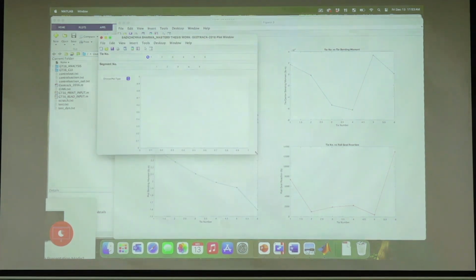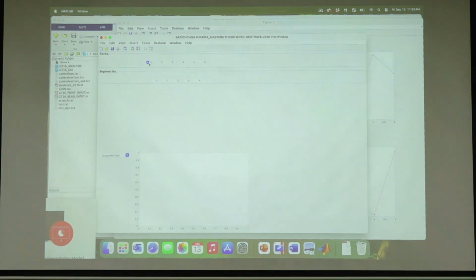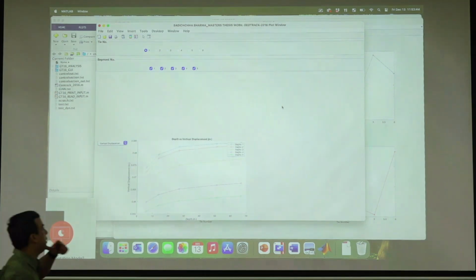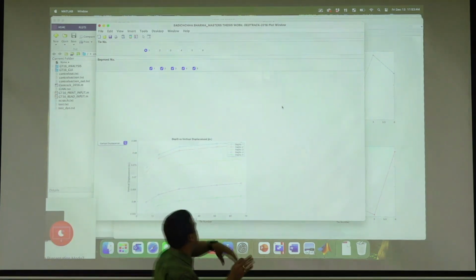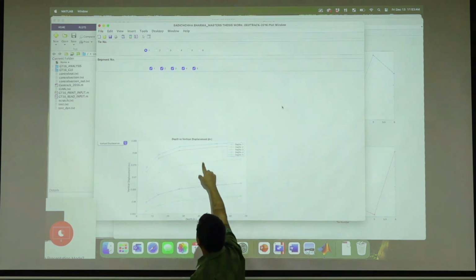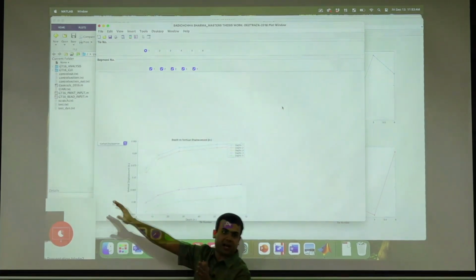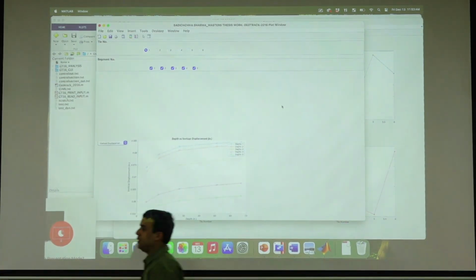But not only that, we developed this open-ended plotting window, where you basically say what tie are you interested in. Okay, I'm interested in tie number 1. What segment? Remember, every tie has 10 segments, and we divide it into 5 because it's axisymmetric, like half of it. And then you select all the segments, and what kind of plots. This is vertical displacement. So now it is plotting the segment numbers, where each segment is. Segment number 1 is under the rail, so of course that has the highest deformation. As we go away, it's in the middle of the track, so it is doing less.